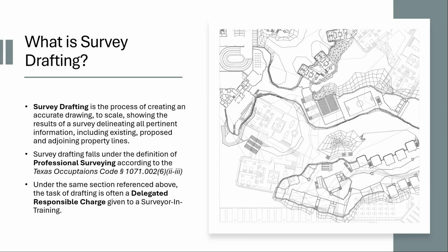But at the same time, as a third example here, we could say, hey, I've thought about property lines, I've looked at the boundaries here, but in reality, my client just needs a topo. They need a topo map provided to them, or these days, probably just a data set, not necessarily a map, but a data set of this area, something that I can slap into Google Earth. I need a KML to show my clients. Well, maybe you don't need to identify all of the structures, all of the trees, or all of the property lines or utilities. Maybe they really just care about the surface, depending on what their study is.